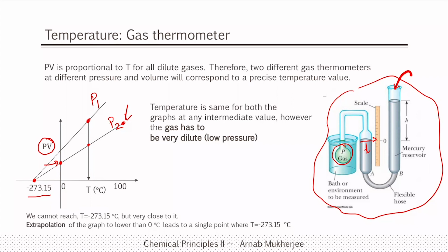So, therefore, we can plot the height here with temperature, and it will increase. So, what is happening is that this height is now proportional to the pressure. The pressure of the gas is now being balanced by the height of the mercury which is there. So, therefore, by looking at the height calculated from this particular value, one can have a measure of temperature. So, you see, we are not measuring temperature directly, we are measuring temperature from properties of other materials. So, either volume of the gas or length of a metal or volume of a liquid.